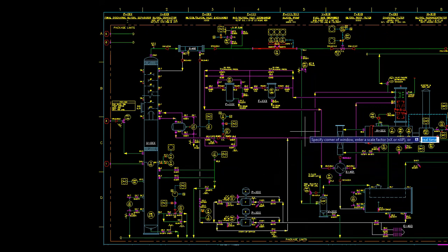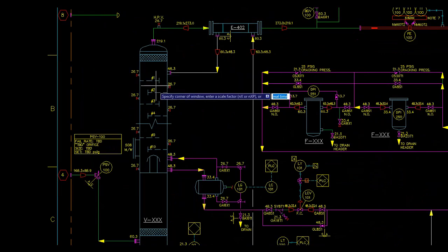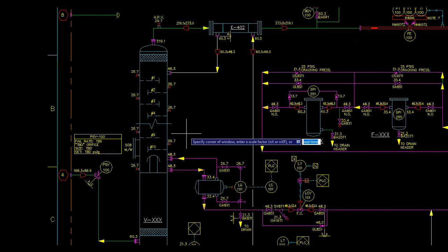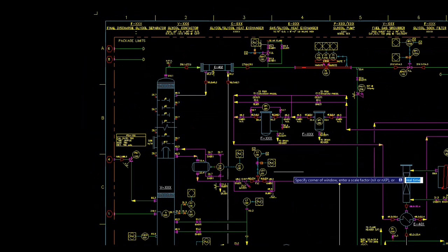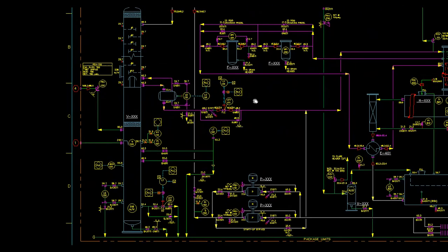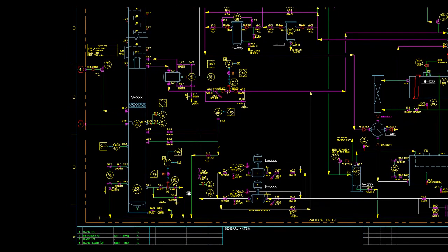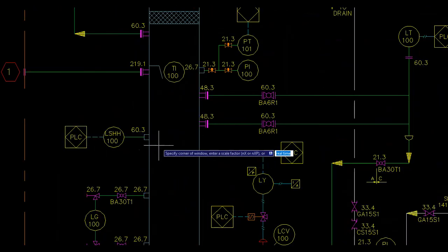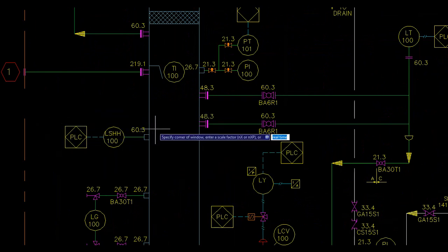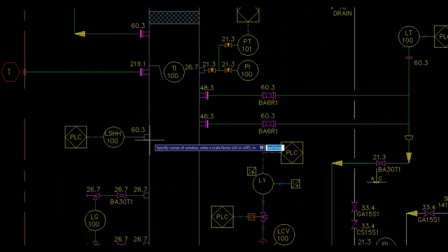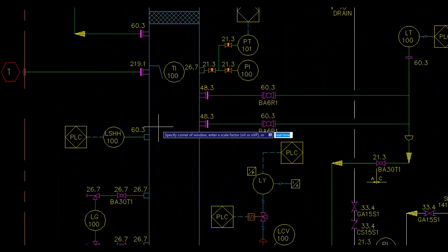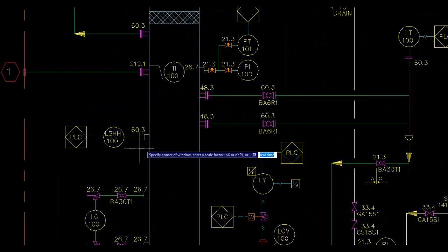Lean glycol is then flowing down in the contactor tray by tray as described before. There are shutdown features available here only for liquid inlets. This is a dehydration unit and we don't want any liquids from the gas. Starting from the separator section in the contactor, this shutdown is for a high liquid level.